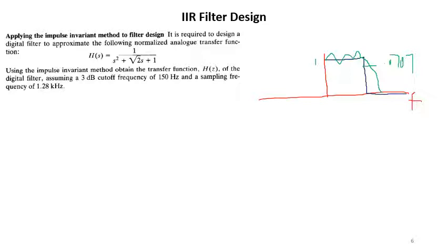That is, you can write, expressing in dB, it will be 20 log of 0.707 to the base 10, so it will result in minus 3 dB, right? So the frequencies where amplitude is 0.707 are called the 3 dB frequency.